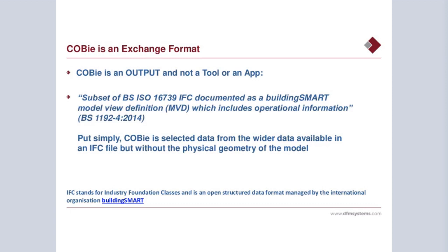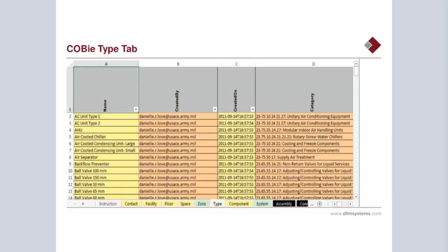It's a standard that's been called up on most BIM projects at the moment, where the owner is trying to make sure that he's receiving the operating and maintenance information for use in his CAFM systems or his maintenance systems at the end of the project. And we've developed means and mechanisms to import information from COBie spreadsheets to populate the information within the safety file itself.